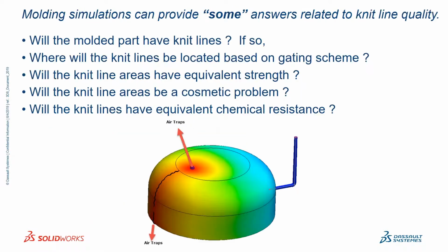So at this point, I think I'll turn it over to Ramesh, who will do some simulation and make an attempt to answer these questions that a designer would have. In picking a gating scheme, will I have knit lines? And if so, where will they be? And is there any information that can help me determine if this is likely to be a structural or a cosmetic problem? So Ramesh, I think if you want to start now, I'll...